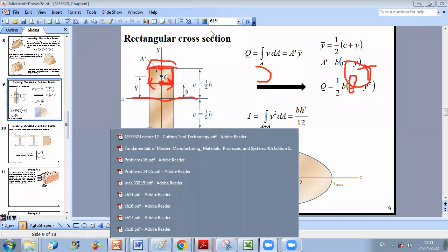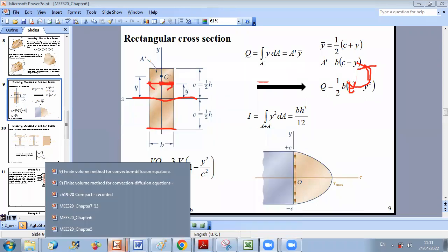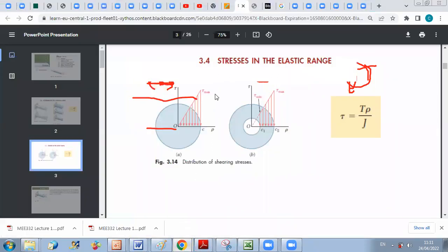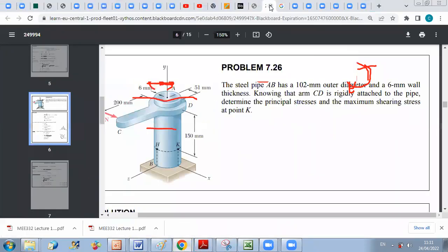So going back to our example, after remembering the formulas we have gone over from different chapters, we can go back now to the problem we were dealing with. We already determined the state of stress at Q, and we said that to determine the state of stress, you can always select any element passing by the point. Once you find the state of stress for this element, you can deduce for any other direction what the state of stress will be.